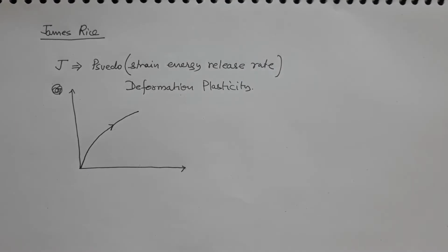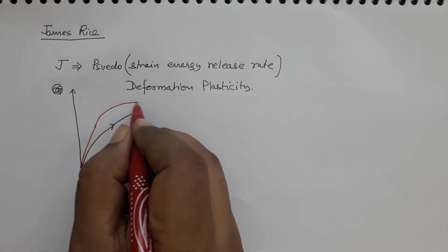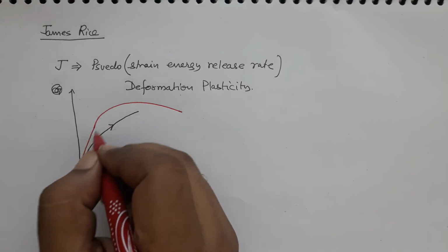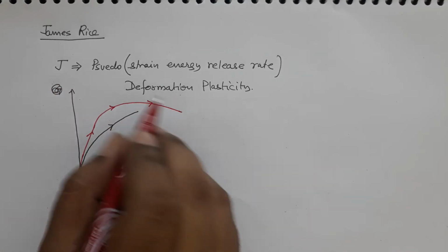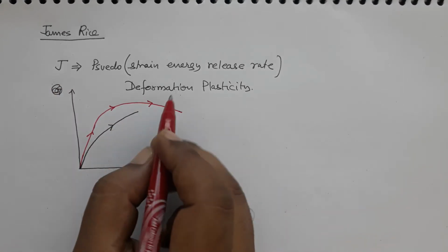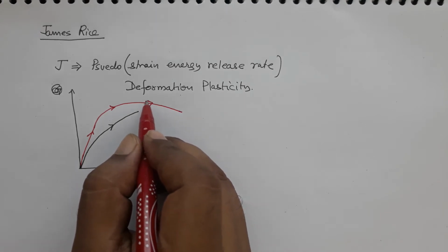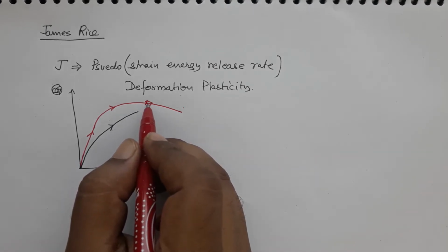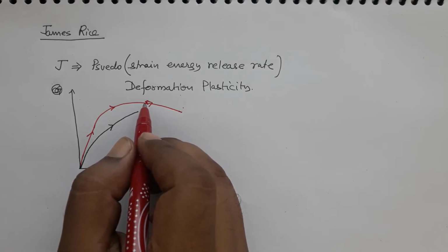the stress strain curve for metallic materials will look something like this. So, as long as you are just pulling it, just loading it, so as long as you are going in this direction, this theory, the J integral is applied, there is no problem. Okay? But if you unload it, or if there is some amount of unloading which usually happens after ultimate tensile strength, and it may also happen in a compact tension. So, in the specimens of fracture mechanics testing, if you have a crack in the system, you might have unloading